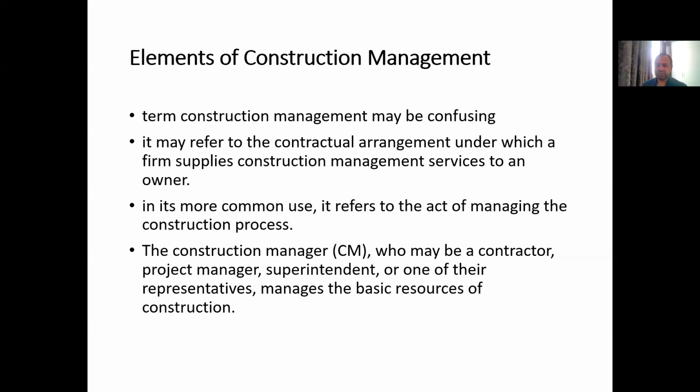We will learn about the scheduling methods in this course: the bar chart method, commonly known as the Gantt chart method, the networking method, which has various types, activity on arrow method, activity on node method, precedence diagramming method, and the resource scheduling, okay, the line of balance method, the linear scheduling method.